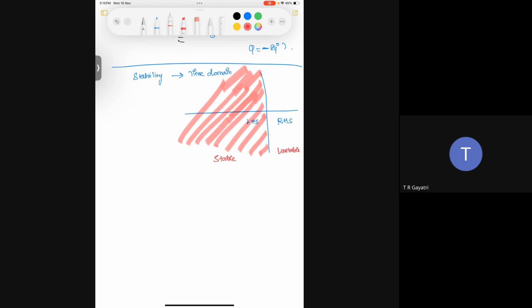So this practice we had in our time domain system, where we chase the poles in the left half of the S plane. When you study stability in frequency domain, instead of poles, you track how the system's frequency response, or output response, runs around a specific point. That is a magic point called minus 1 j 0. Here it is. So we would be interested in this point instead of the origin. We would be interested in this point.